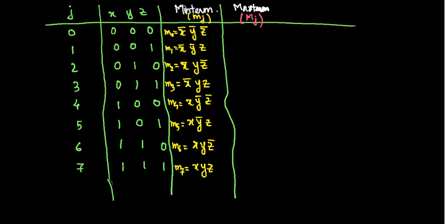So it is represented by capital M0. In a max term, it has to be the product of sums. I mean there is no product here, but each term is expressed as sums. The rules are reversed there. You make the variable prime when it is 1, the reverse way around.